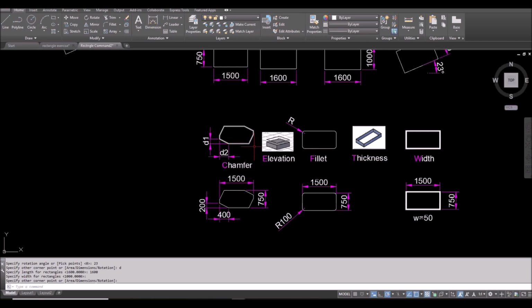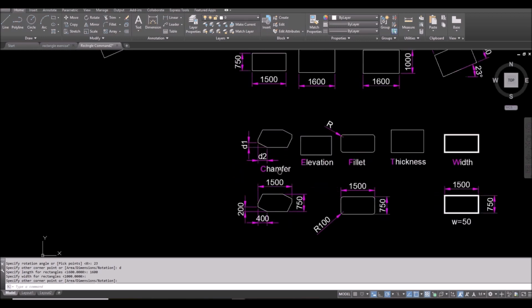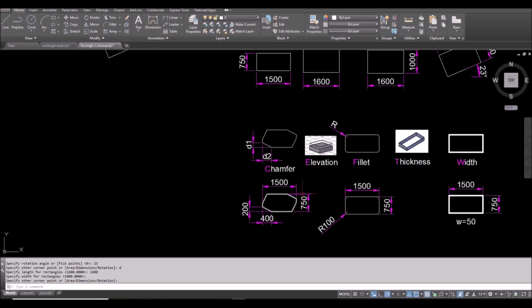And then we can draw a rectangle with specified properties, for example a chamfered rectangle. For example, if I want to draw this rectangle, I do this. First, I will type REC spacebar, and before continuing, look at it here. Current rectangle mode, rotation 23, because we used it before, so it's still a rotated rectangle. To reset it, all you need to do is specify the rotation later when there's an option.